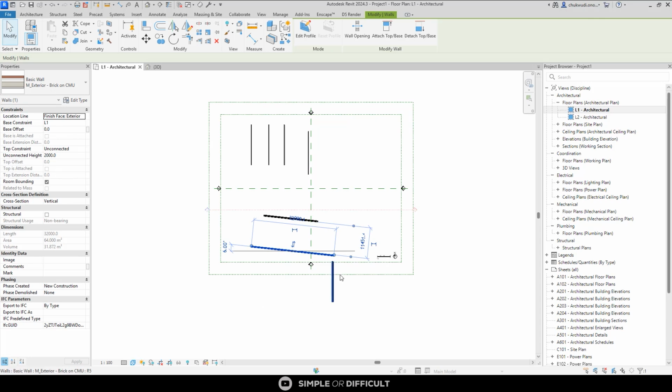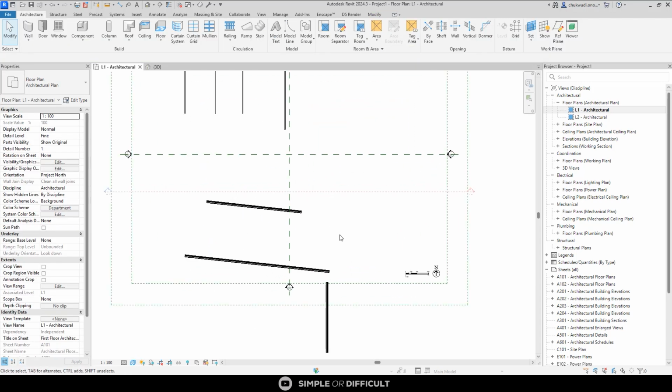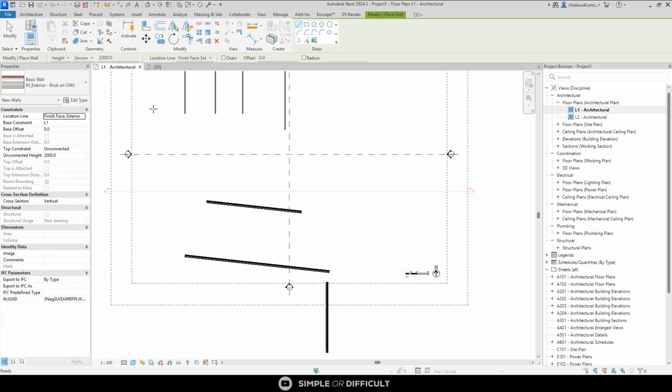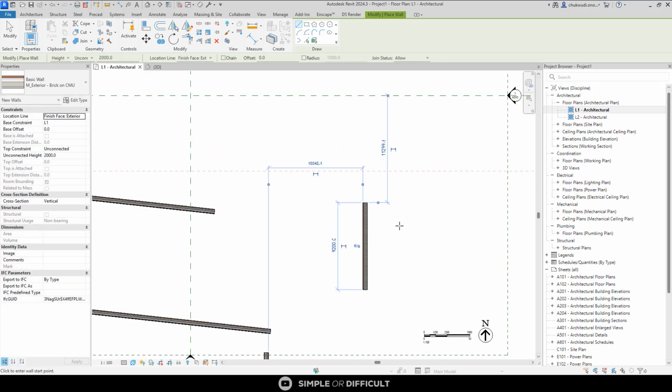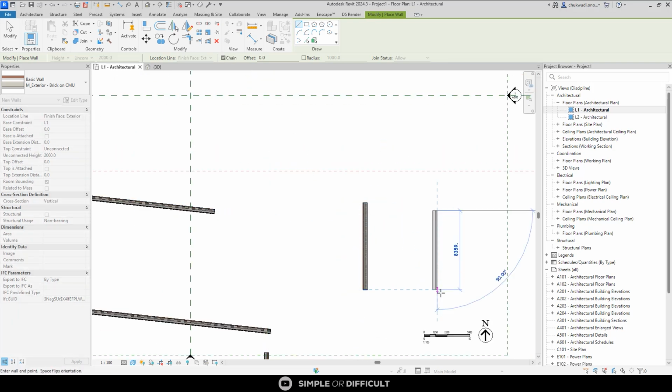When I select it, okay, right? So when I click on this, Revit is going to tell me click enter for a start point. You can either click enter or you can just left click on your mouse. Okay? It is also telling me vertical flip, vertical space flip orientation. So if I hit space, it is going to flip it for me. So it is trying to suggest the things you can do when you are modeling in Revit. Okay, that is it for the status bar.